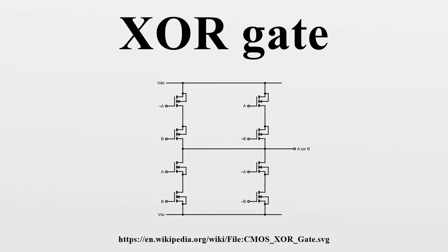Pseudo-random number generation. Pseudo-random number generators, specifically linear feedback shift registers, are defined in terms of the exclusive OR operation. Hence, a suitable setup of XOR gates can model a linear feedback shift register, in order to generate random numbers.